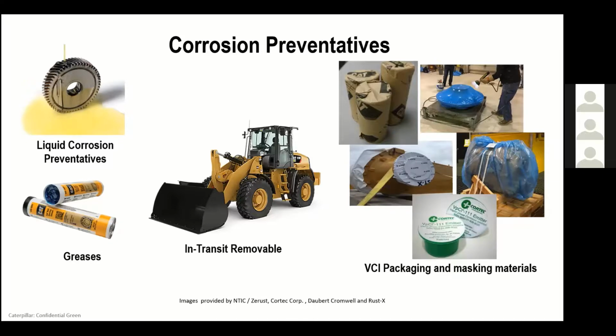And then down below, these are emitters. And so a lot of times people will take some of their toolboxes, and because there's not air moving across it, they'll put in some of these emitters to help preserve some of the different types of tools they have from further oxidation.